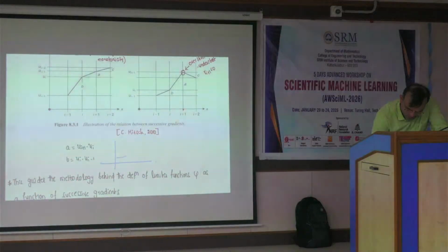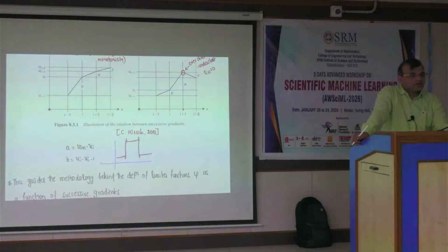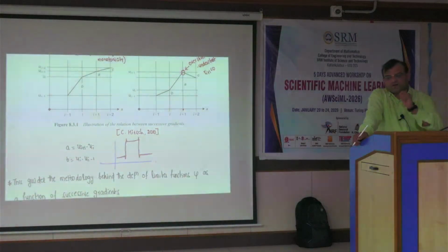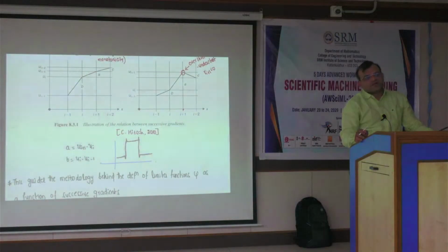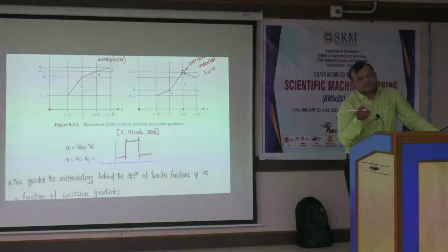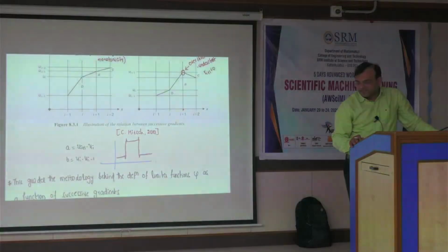For example, if you take a square pulse and approximate it by a numerical solution, you may encounter a small bump, a wiggle. The solution looks good everywhere apart from where the transition is happening from discontinuous to continuous and continuous to discontinuous, because the slopes will vary with respect to this scheme.